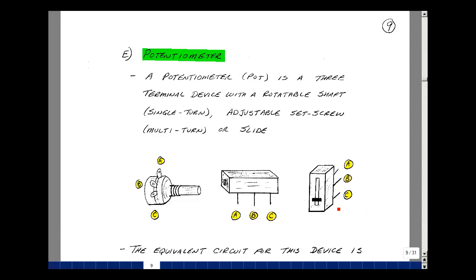And then in our lab, we're going to be looking at another kind of potentiometer. The way this thing's made inside here is that there's a track of carbon and a resin that creates a resistance between terminals A and C. With terminal B, there's a connection with the shaft of a piece of carbon that's pressing on the track between A and C. So you're getting a percentage of the total resistance between A and C. Now with this type of potentiometer, you're just doing one rotation and going from one end to the other end.